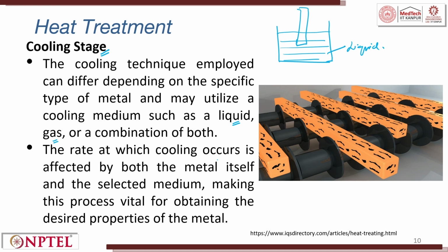The rate at which the cooling occurs is affected by both the metal itself and the selected media. So, liquid media, solid media, or a gas media, you can choose. Solid media, you can also try to have some salts and then you can quench it in that salt. So, then there is a diffusion of the salt also on the surface.